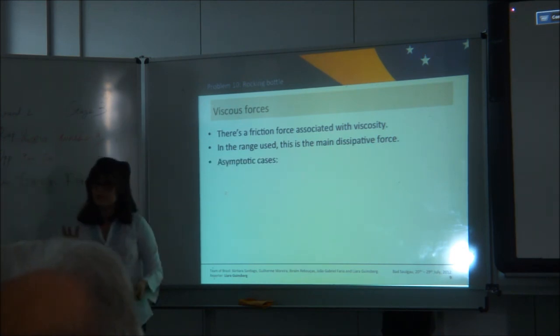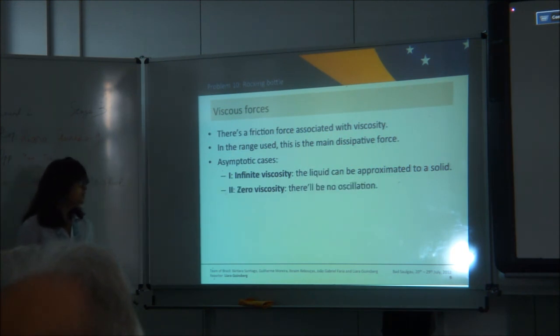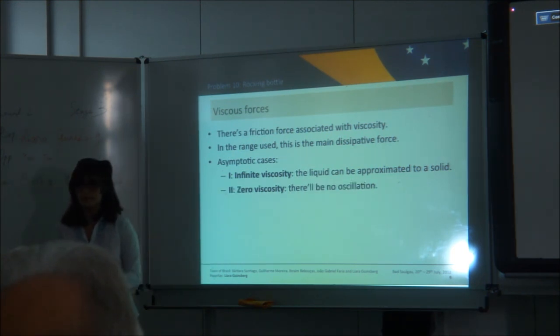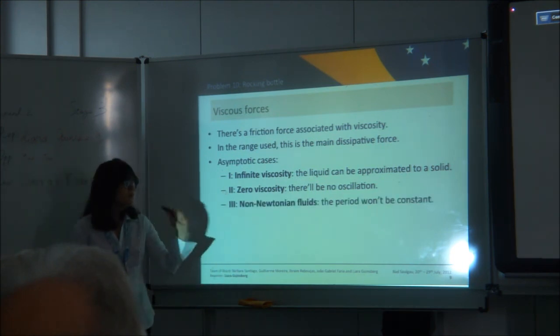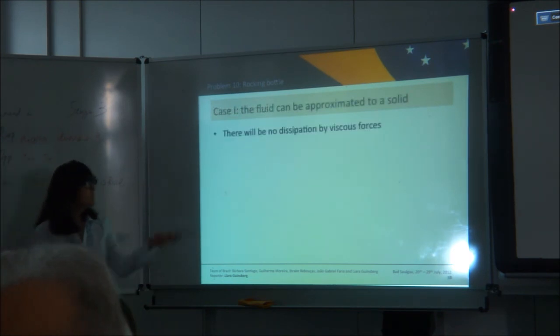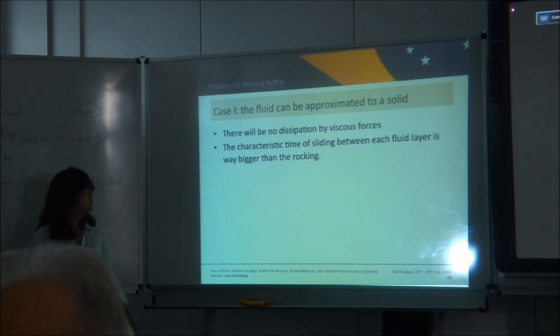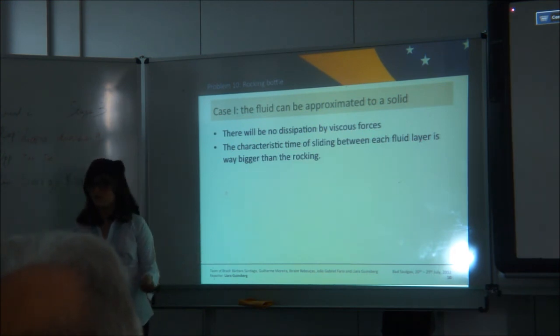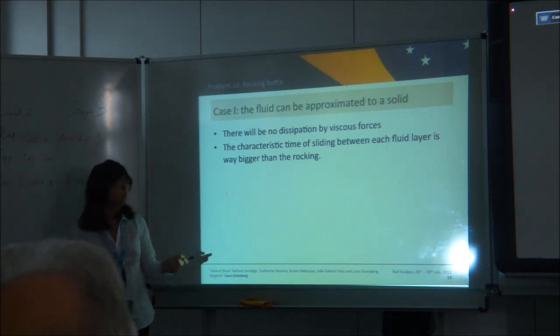And we can have 3 asymptotic cases. First, the infinite viscosity, when the liquid can be approximated to a solid, the zero viscosity, when we will not have oscillation, and the non-Newtonian fluids, when the period won't be constant. In the first case, there will be no dissipation due to viscous forces, because the characteristic time of sliding between each fluid layer is way bigger than the rocking itself.